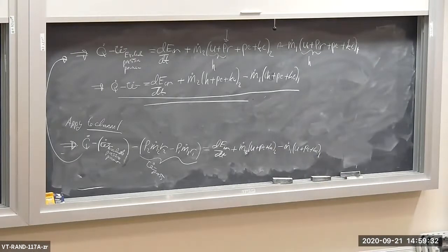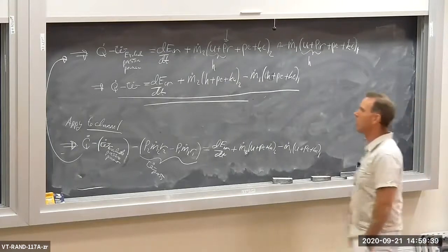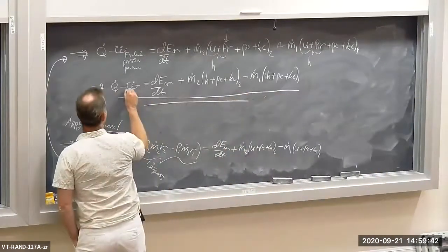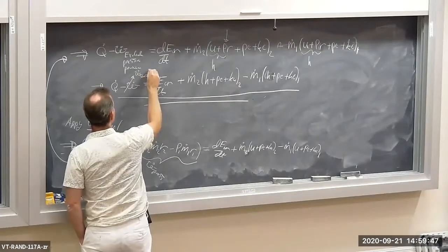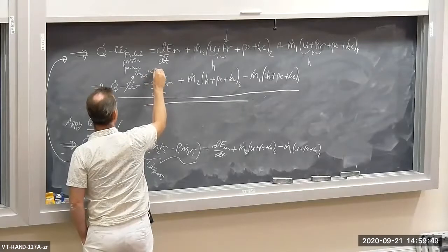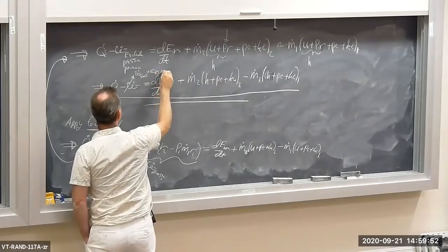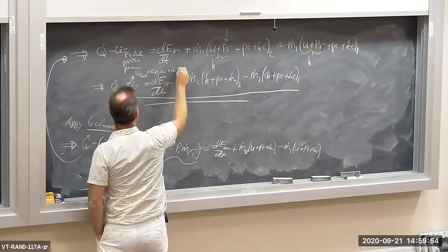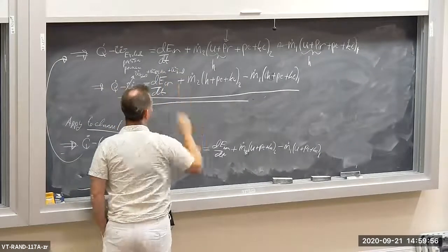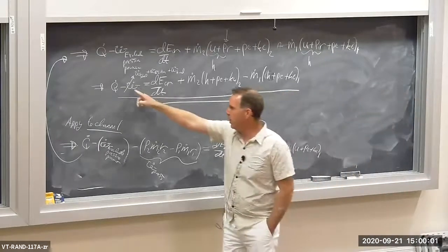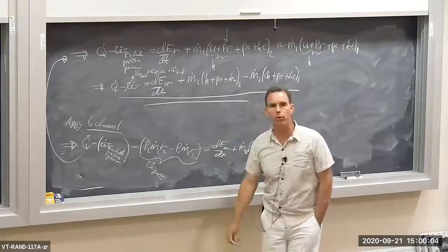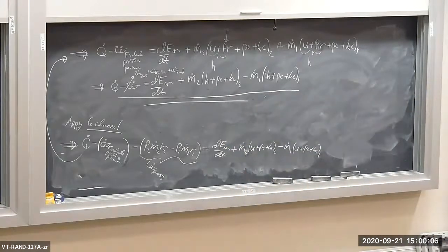And we do that by substituting H in place of specific internal energy, U. And the W dot here, remember, is W dot shaft plus W dot electric plus W dot boundary. No pressure power in this term. The pressure power has been swallowed up on the right-hand side and the U's became H's.